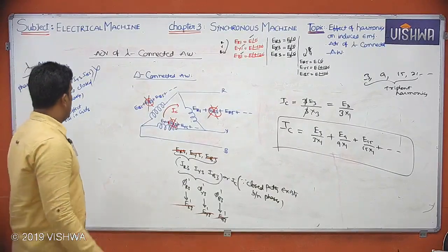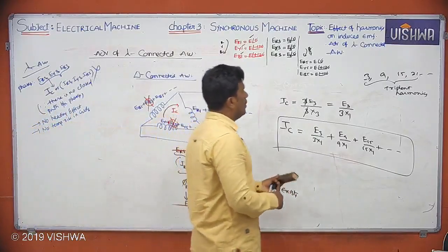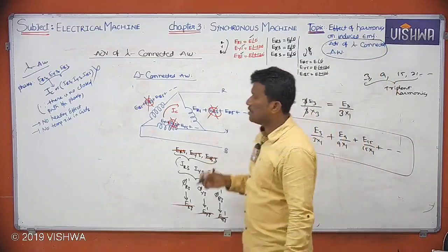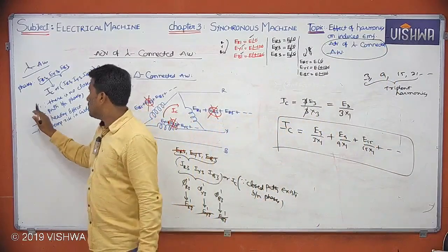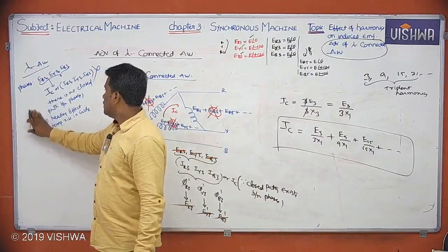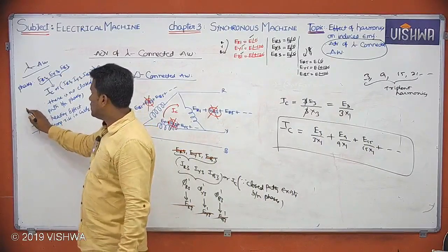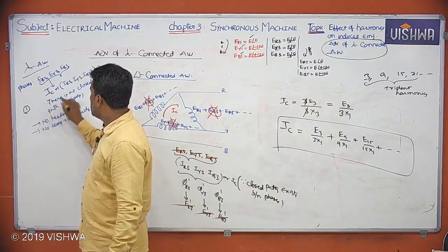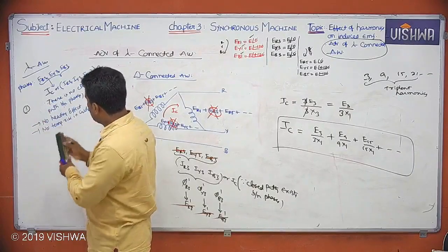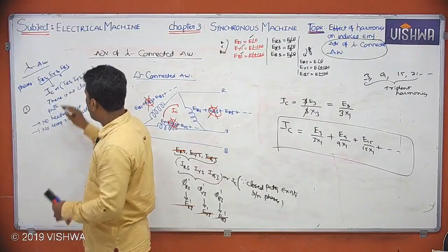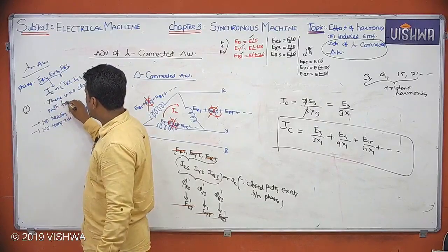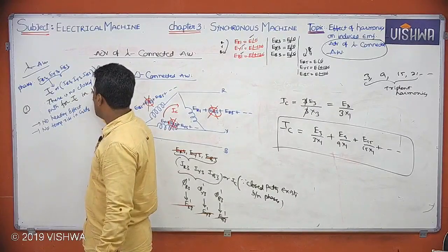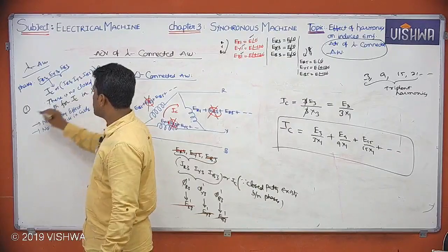Now tell me, our last conclusion, our heading here: advantages of star connected armature winding. Number one, what is the advantage here? I can write here: advantages. There is no closure path for circulating currents in star connected armature winding. That is the first point.